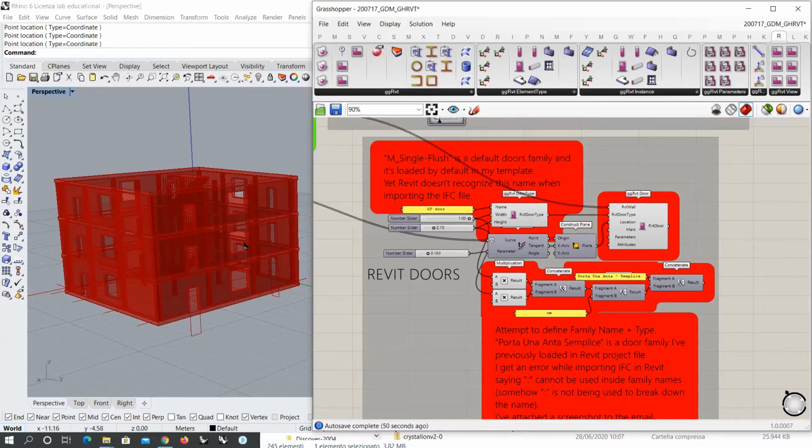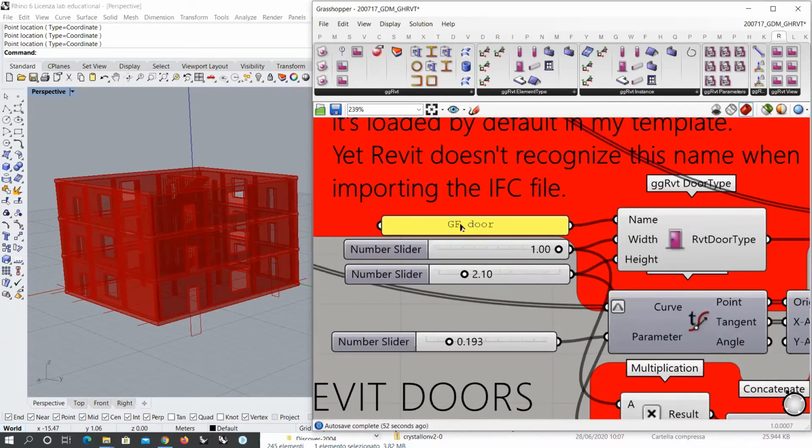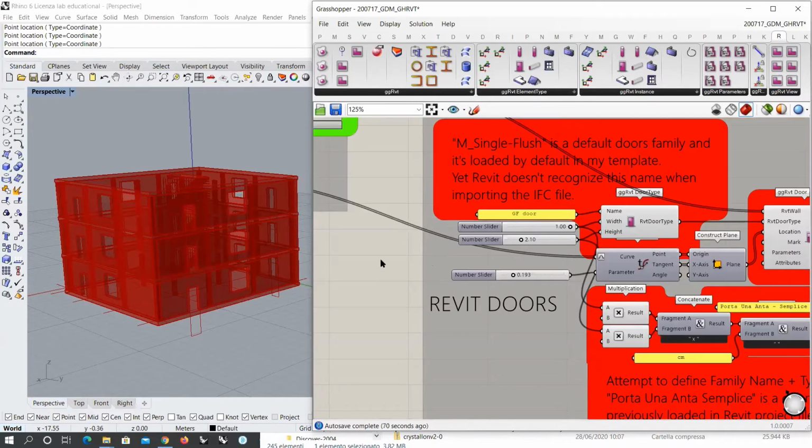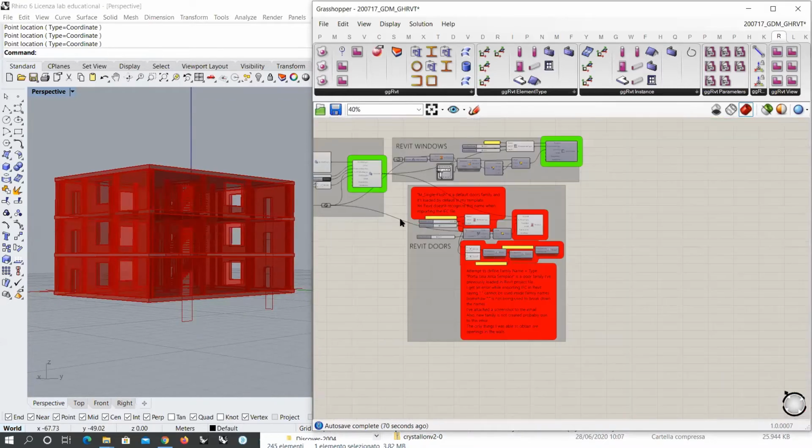So you can select all the doors that must only appear on the ground floor and get rid of them level by level, selecting with one click all the instances of that type of door. So with one delete operation, you are going to delete all the doors that are not necessary at the corresponding level. Okay, so this is something like a trick for bypassing this kind of thing,